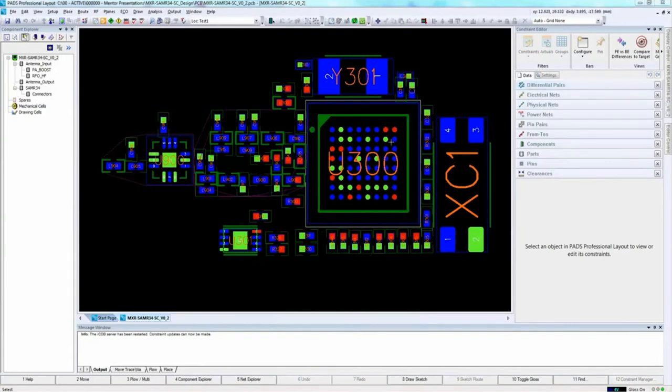Now, moving on to traces, vias, and other PCB components, the use of vias is essential in most routings, but the designer has to be careful in using them. They add additional inductance and capacitance, and reflections occur due to the change in the characteristic impedance. So vias also increase the trace length.